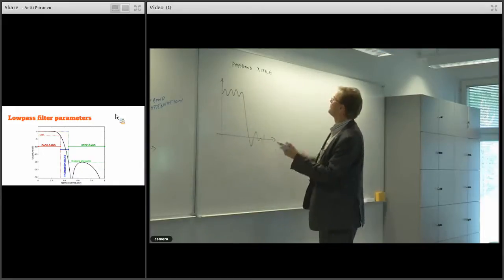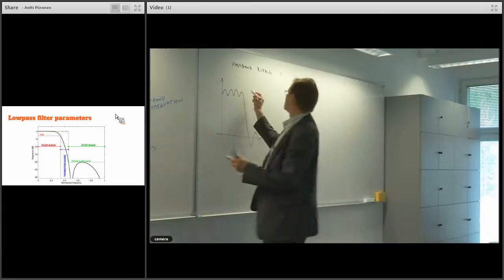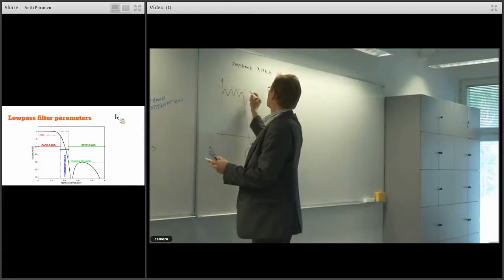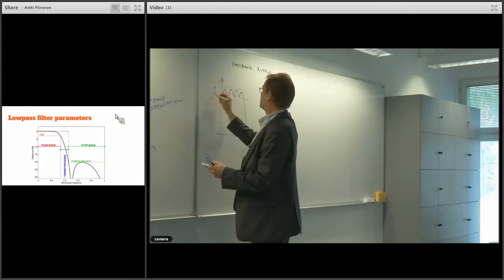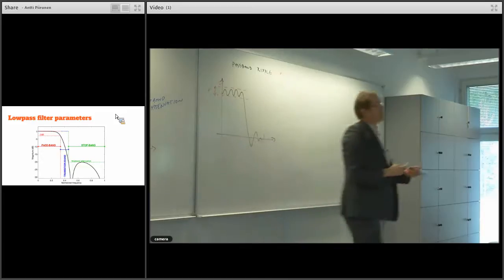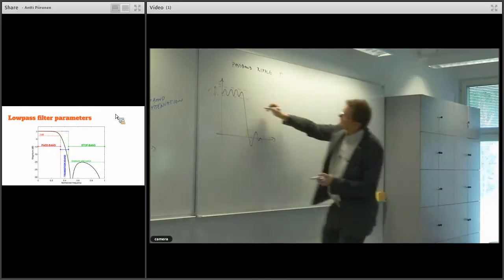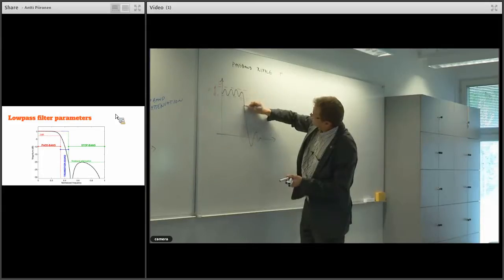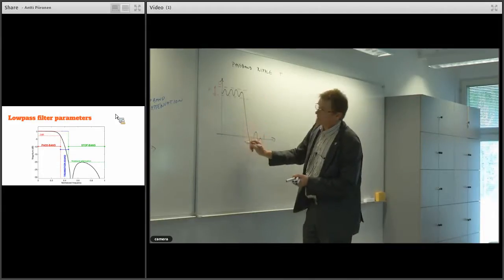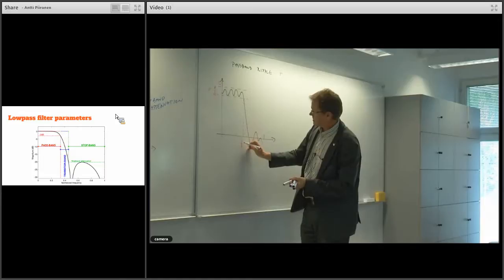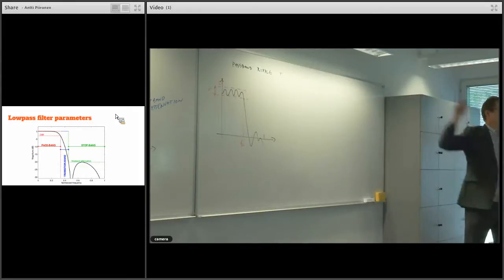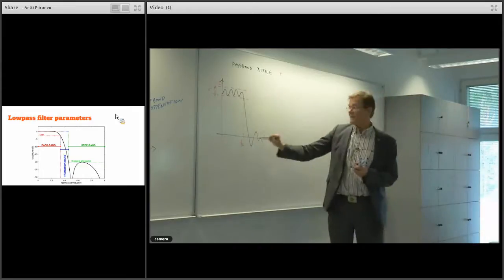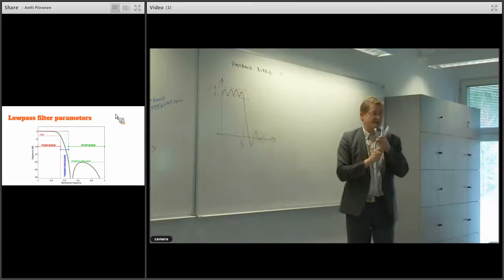Ripple R. Okay, 0 dB, and that would be R dB here, marked in decibels, which also means that our passband corner frequency would be here, where the ripple stops and the transition band starts. That's where the corner frequency is defined in this case.